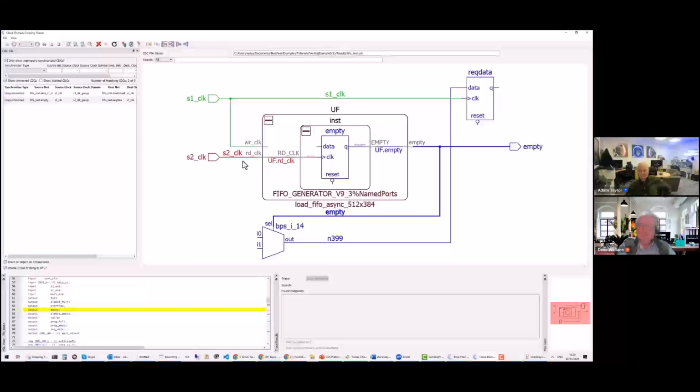And because of this grey cell technology, as we were talking about, and as I showed you in the schematic element, it's showing that there's an inadvertent clock domain crossing, which we need to go away and correct. But again, we can correct it relatively easily. But again, it changes the functionality. So if you're changing the functionality, you've got to go back and rerun a regression suite of tests. So this brings me to the end of my relatively quick demonstration.